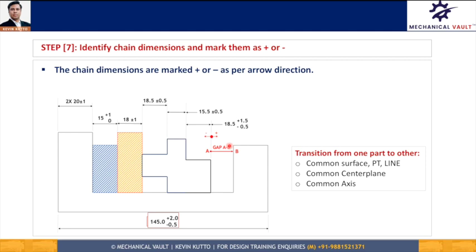Now, what happens if any link or dimension is missing in the engineering drawing? That means that dimension or tolerance itself is not provided on the engineering drawing. That's where we have to collect dimensional data from the manufacturing process. That process should be a statistically stable process, and we study the actual variation in that statistically stable process for that dimension and then include that in our stackup analysis. Or, if that is not possible, get that dimension added to the engineering drawing. We cannot just take an uncontrolled dimension from the CAD model and add that into our stackup.